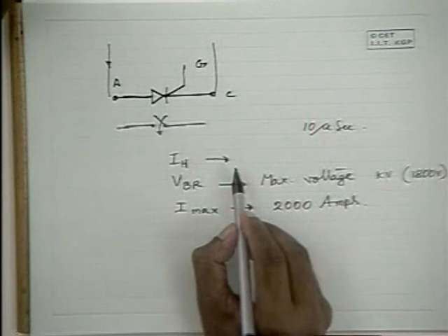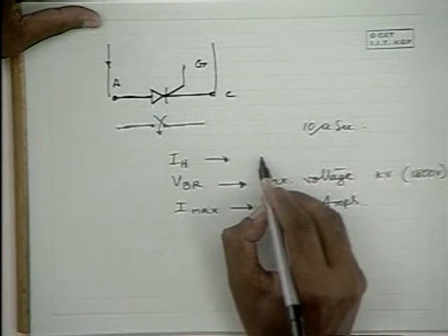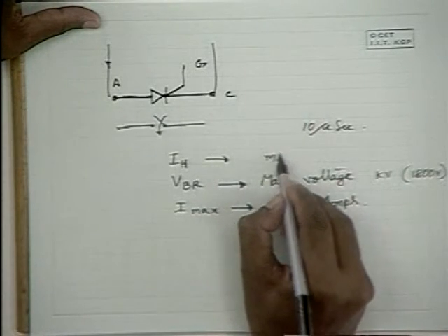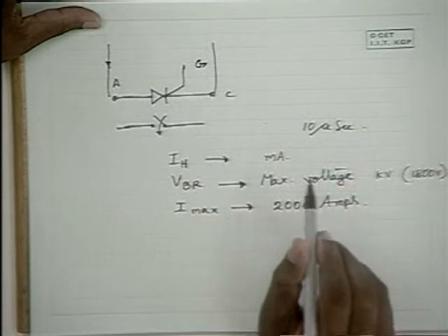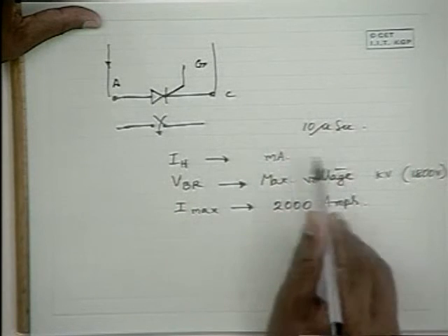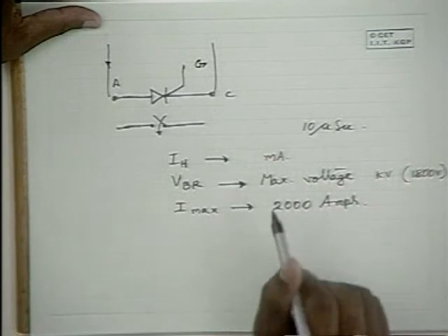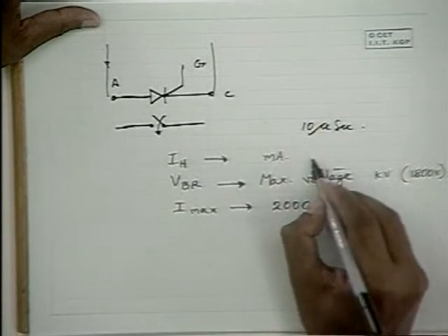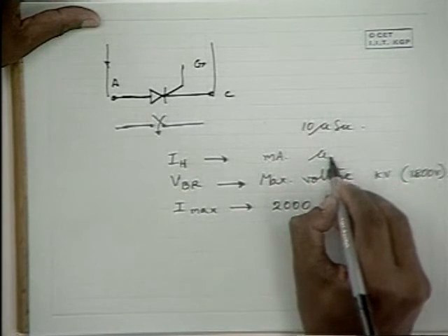The holding current is very small, of the order of a fraction of a milliampere for zero gate potential, and even for appreciable gate currents, it is a fraction of a milliampere, of the order of microamperes.